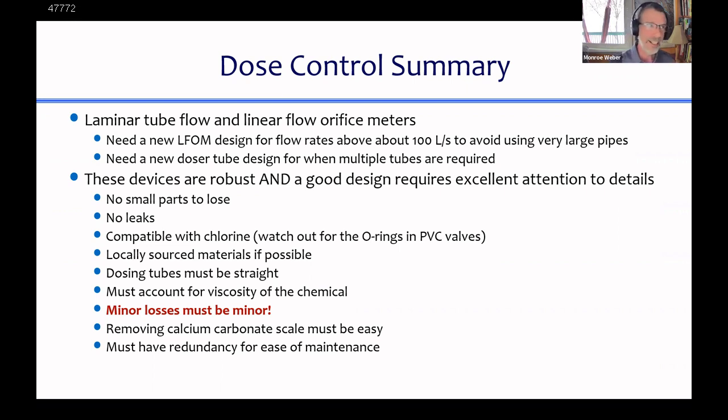And the reason is because you can buy solid granular calcium hypochlorite, and the amount of chlorine per mass of calcium hypochlorite is much, much, much higher than the amount of chlorine per mass of bleach. And so if you're thinking about transport and the cost of transport of getting this chemical to your site, to your water treatment plant, the costs are lower if you can use calcium hypochlorite. So that's the reason why we're using calcium hypochlorite in Honduras, well, in Central America, and indeed in India as well. And that is the end of that.